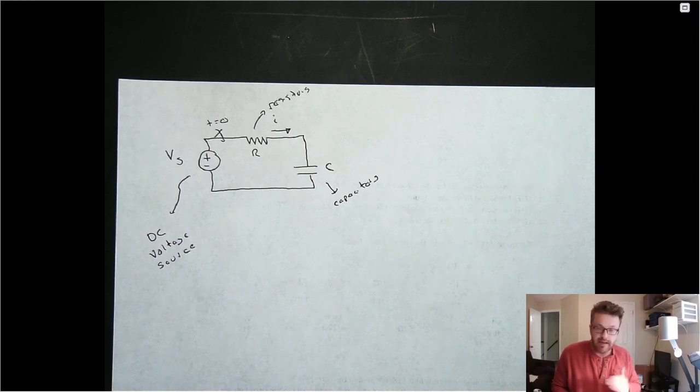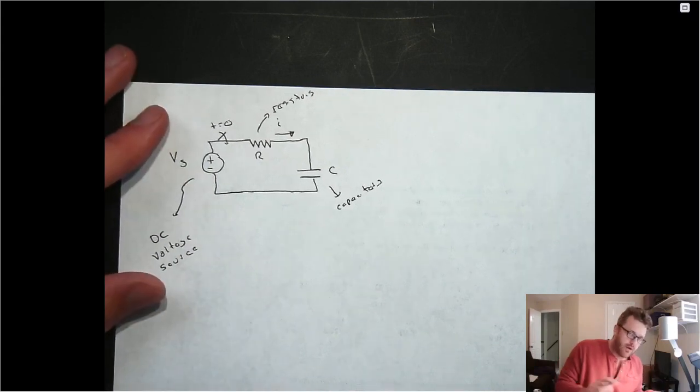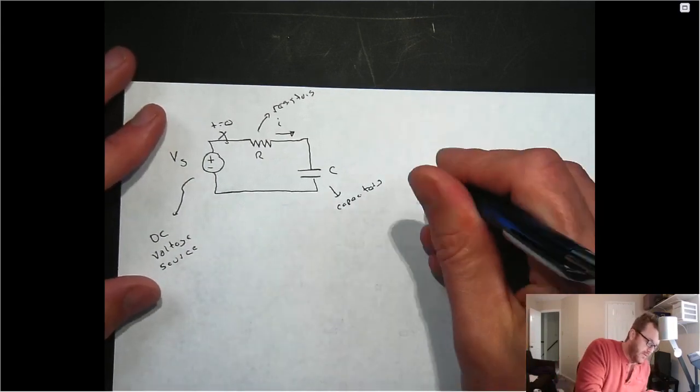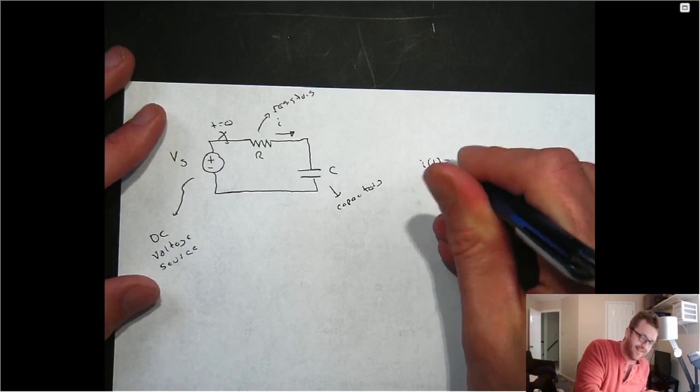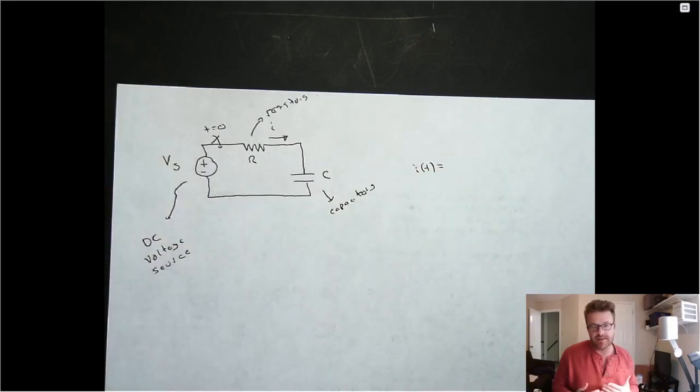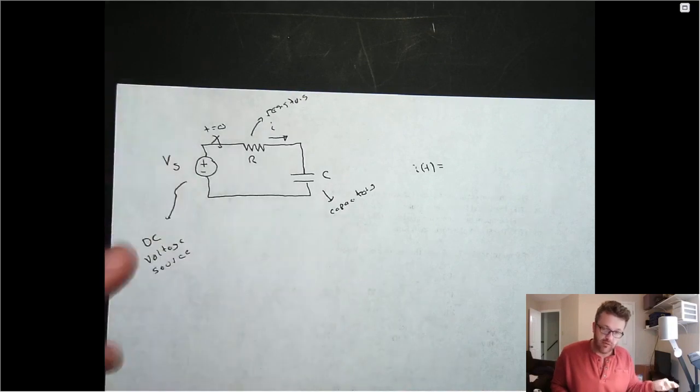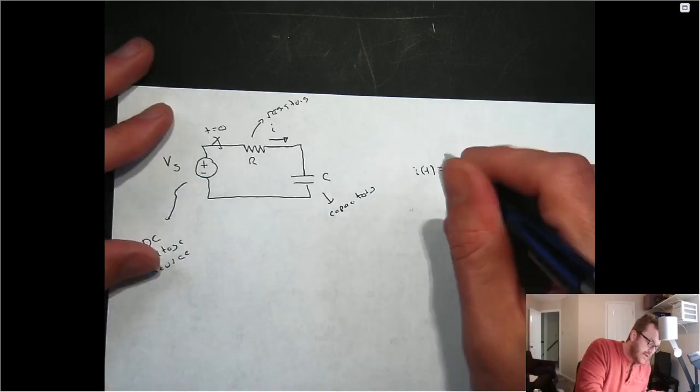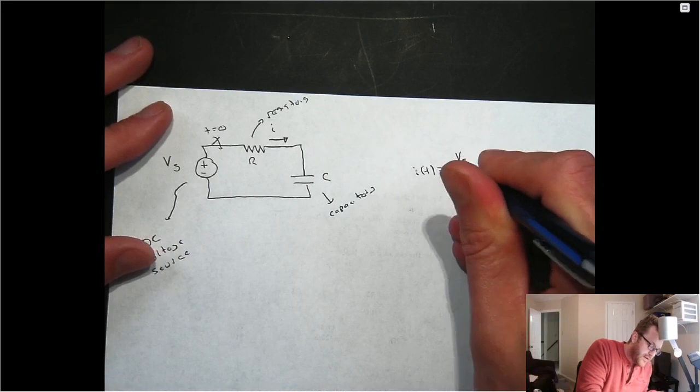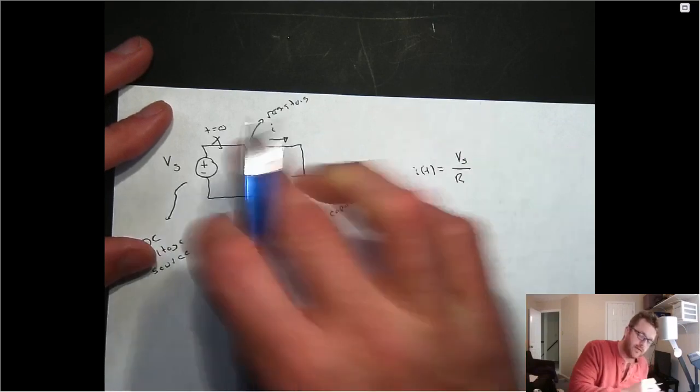And after the capacitor has been fully charged, that is referred to as the steady state period of operation of this circuit. So if you look at the actual diagram that I gave you, and hopefully I won't make a mistake on this, the current in this circuit as it varies over time, all referenced from t equals 0, the point at which the DC source is attached, is going to be whatever the source voltage value is, divided by the resistance value in the circuit.